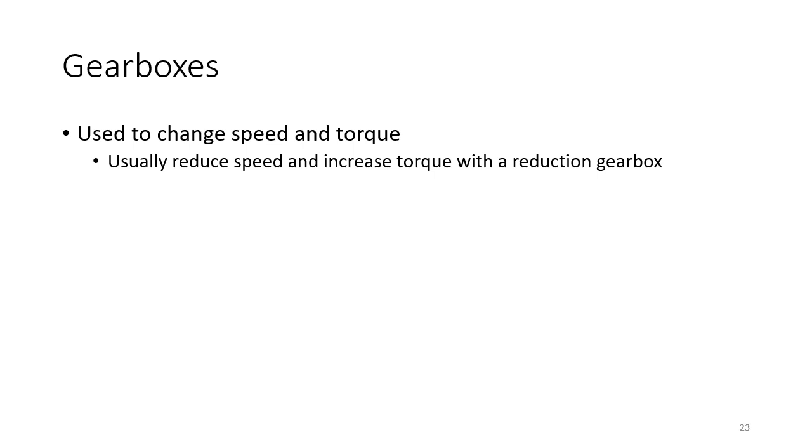You think about a typical motor that might be running at 3,600 RPM. It's rare to need that full 3,600 RPM. So a reduction gearbox will allow you to reduce that speed, but correspondingly increase the torque. So this can also affect your motor sizing, of course. By knowing what your speed and torque is, then choosing an appropriate gearbox, that would allow you to choose a smaller motor potentially, but still get the required torque you need by using a higher speed motor and then the reduction gearbox.